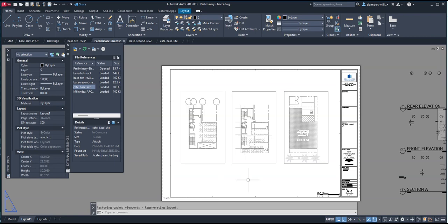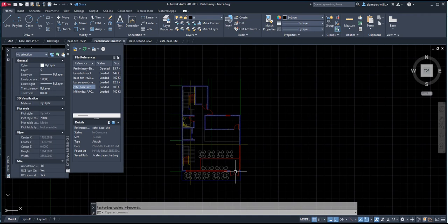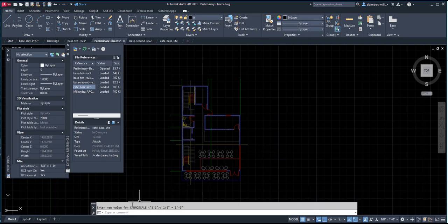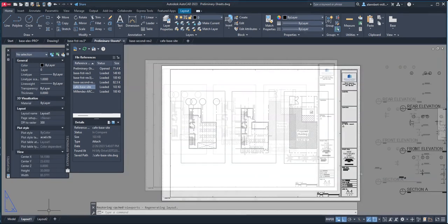On paper space, our LT scale is also one, and then we put in our PSLT scale, and it's supposed to be also one, enter, and then back to model space, we must put in MSLT scale, and it must be one, and then the last thing that we need to do is make sure that the annotation scale here is set to 1/8 of an inch, okay, so that it matches. Let me save first. It matches our layout.